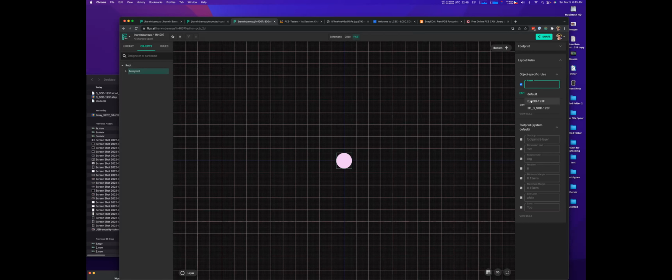On the bottom left of the canvas, this is how we manage the layer view of the PCB. So you click on the layers here, and I just want to hide the base and the mask so that I could just see the pads here. If I click this pad, this belongs to the cathode, and this one belongs to the anode.